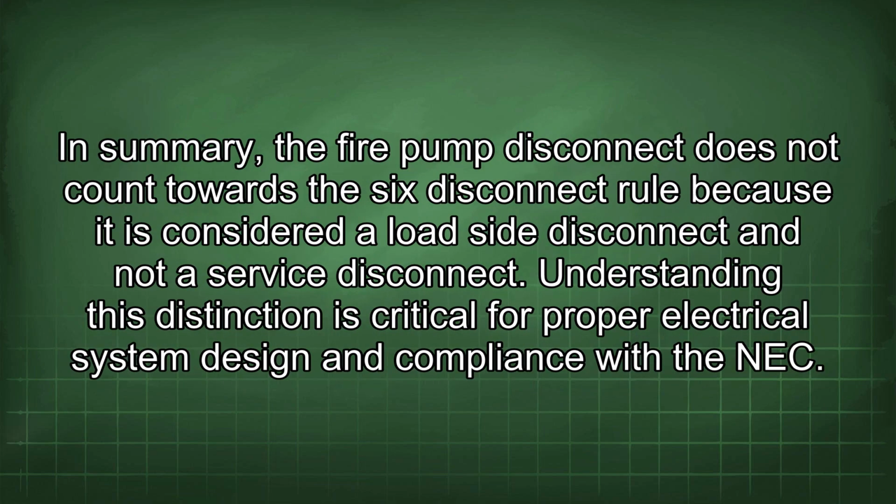In summary, the fire pump disconnect does not count towards the 6 disconnect rule because it is considered a load side disconnect and not a service disconnect. Understanding this distinction is critical for proper electrical system design and compliance with the NEC.